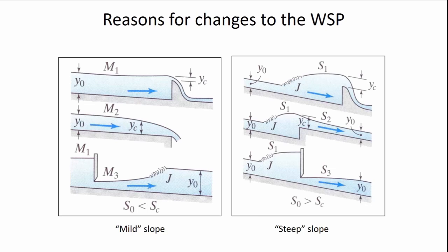So here we've got a supercritical slope, a normal depth, and then it has to go through a hydraulic jump to match up with the S1, because the normal depth should be below the critical depth, but this is forcing the flow depth to be greater than the critical depth, and so it has to go through that hydraulic jump to match it.